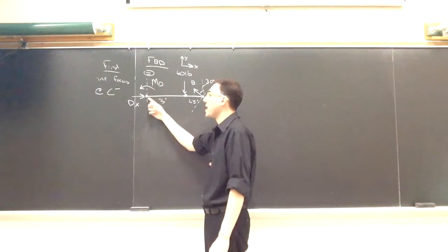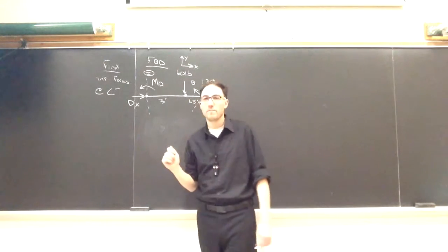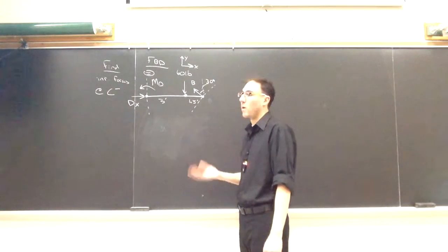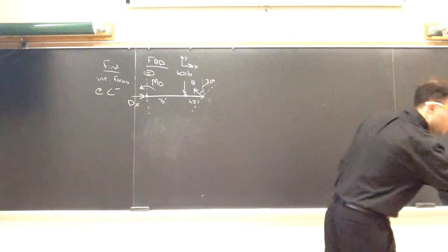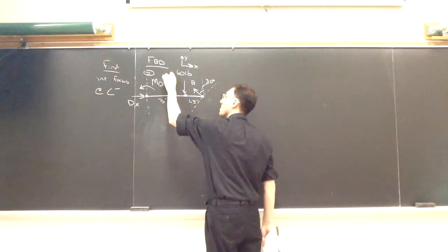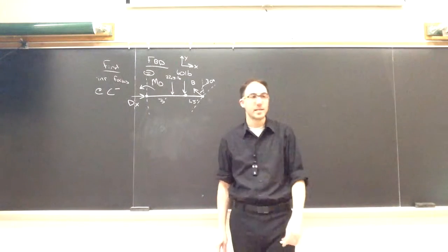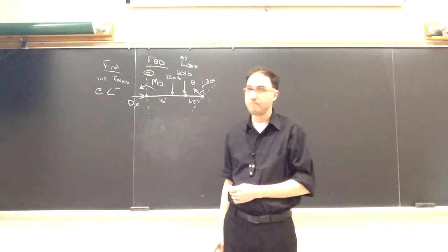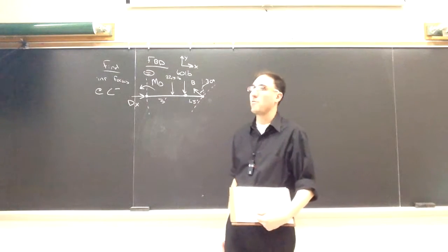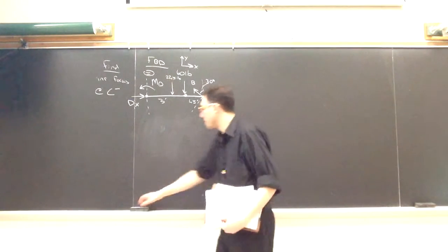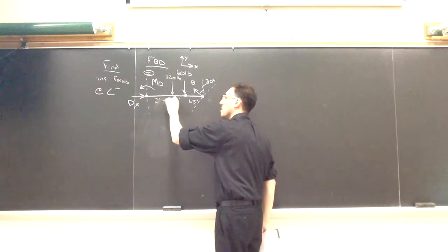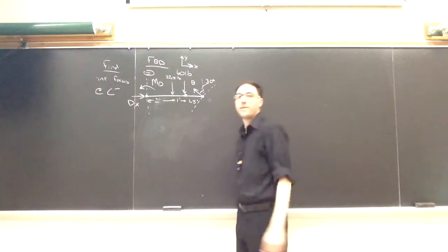So if I look at the triangular part that goes from D to C, that right triangle has a base of 3 feet. It has a height of 15 pounds per foot. So the area is 1/2 times 3 times 15. So for my left triangle, that's going to be 22.5 pounds. Again, this is only the right triangle with the base from D to C. And I know for a right triangle that its centroid is located 1/3 of its base from where the right angle is. The right angle is at C, which means that where this point load is acting is 1 foot from C and 2 feet from D.